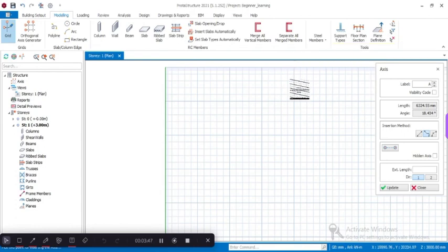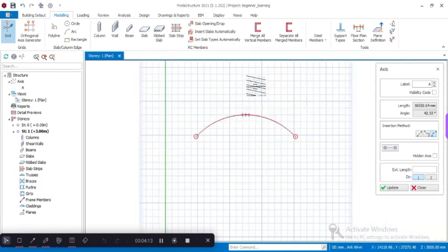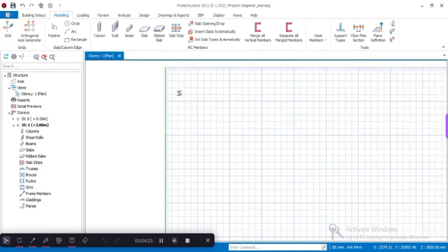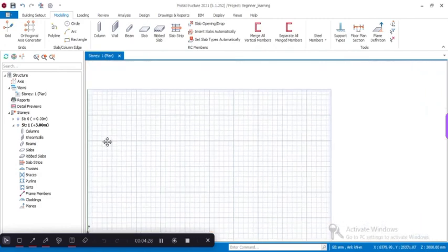Let's go to inserting curved axis. So when you click a point and you click another point on your axis, then you drag it. This is where you want your arc to be, towards the negative or the positive end of the y axis. So if you want it positive, this is it. If you want it negative, so let me say F2, 3000, okay, positive. That's our curved axis. Or you can left click. So we've created a curved axis now. Let me delete that.